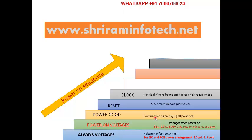See, in this chip, this one is called the PCH, and the clock section is inside this PCH. There is no separate IC. Only one crystal is connected. This is a 25 megahertz crystal, which generates a 25 megahertz frequency given to the PCH, and inside the PCH there is a multiplier which generates different frequencies given to different sections, internal to the PCH and external, like the CPU, RAM or wherever it may be required.